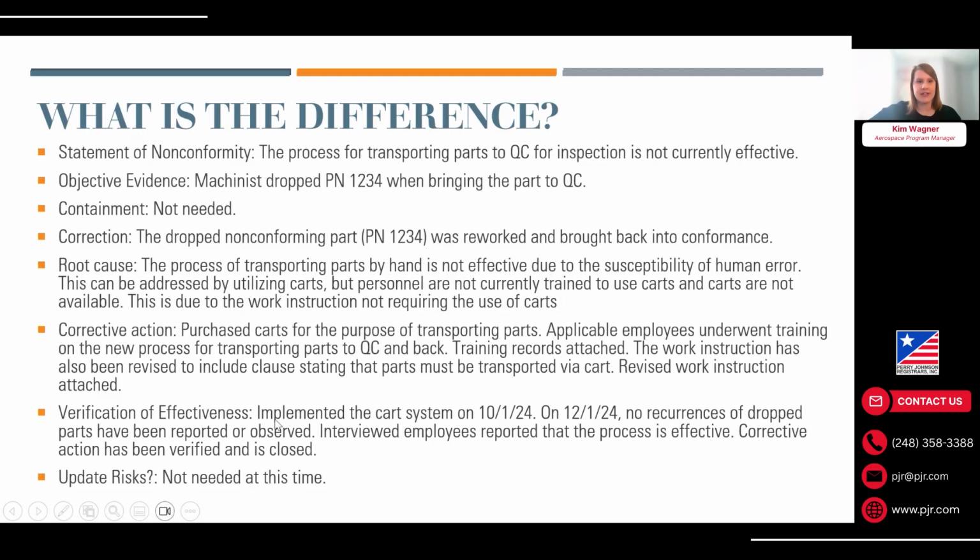Then we have the root cause analysis, which says the process of transporting parts by hand is not effective due to the susceptibility of human error. This can be addressed by utilizing carts, but personnel are not currently trained to use carts and carts are not available. This is due to the work instruction not requiring the use of carts. So in this root cause analysis, we're considering human factors, but we're not stopping there, right?